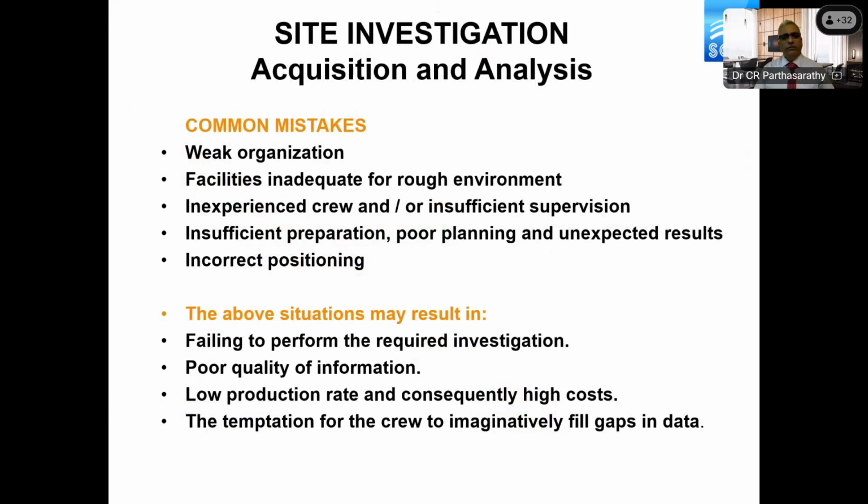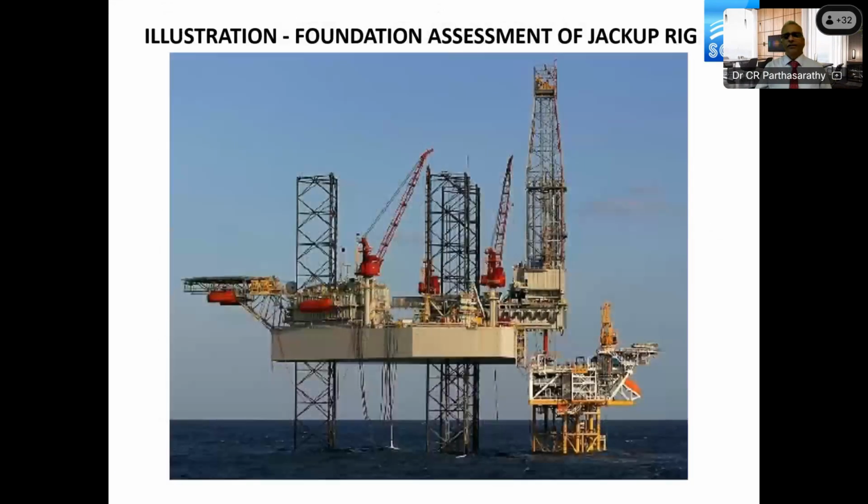These common mistakes result in failing to perform the required investigations and poor quality, and one of the important things is the temptation of the crew to imaginarily fill the gap. Now just imagine you miss out the crustal layer and you tend to fill the gap, then you are actually losing out on whether the rig will punch through or not. So the sensitivity is that we need to have a continuous record, particularly when assessing the performance of the jackup rig.